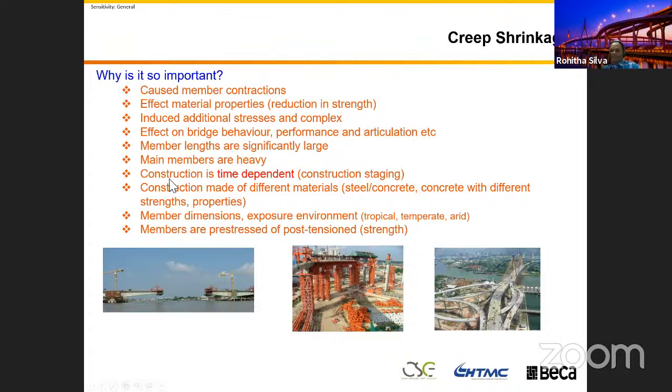For the construction, we do the construction staging analysis, especially to calculate the camber curves, and the creep shrinkage assumption, the way we handle them, has a significant impact on the actual construction. Whether you build the composite material as steel and concrete or concrete, you still need to consider the creep shrinkage effect. Another thing is what we call the differential shrinkage effect in the